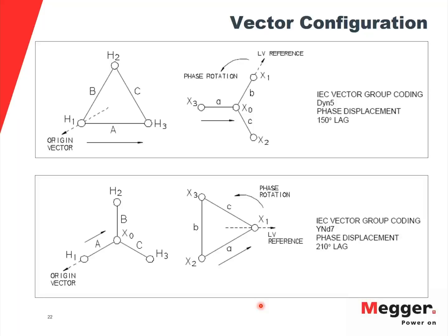When we talk about the Megger transformer ohmmeter, the test set specifically designed for winding resistance, the difference, in addition to your regular 10 amp or 50 amp current, is that it has a discharge circuit inside the unit that is capable of dissipating the energy stored in the inductor or the coil, whereas a DLRO does not have any discharge circuit, which means that yes, you can run the test,